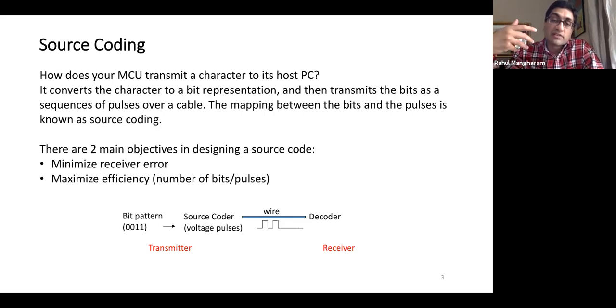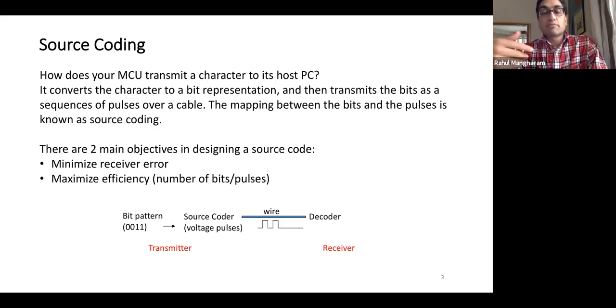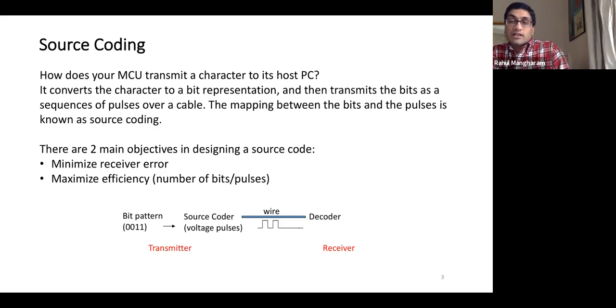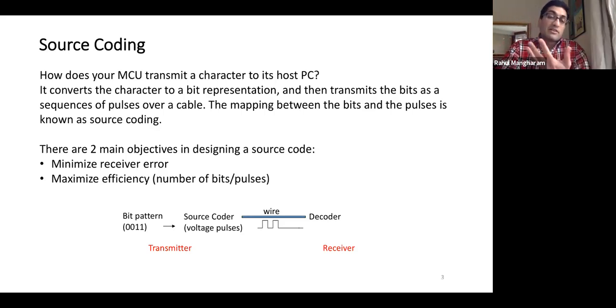And then when the receiver receives it, the receiver says, okay, well, I've captured some kind of waveform, and it has to basically capture the energy from that waveform. You can think of capturing energy as a capacitor on the other end and saying, well, how much charge did I get in the last time step, for example, or whenever the start of some kind of analog wave was coming in, right? So it does not know whether it's a 1 or a 0 yet, right?